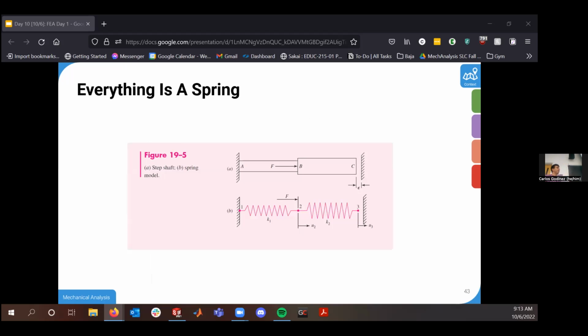So basically, as a very rough approximation of that entire process, and representing it more visually rather than in matrix form, we're treating each element as if it's a tiny spring. Depending on how many degrees of freedom we care about, we have different spring constants in different directions that correspond to the element's geometry and material.